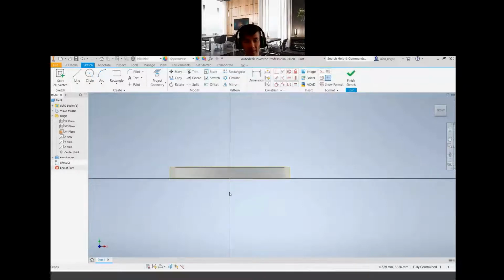Okay, so the next one that I would like you to do is you go to slice the graphic. Okay, because we want to create our sketch on the middle part of this feature itself. So it's F7. You can press F7, or you go to the bottom part of here, your status bar here. Then you will have this slice graphic. So click on it.